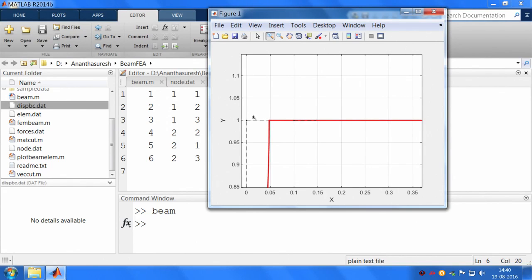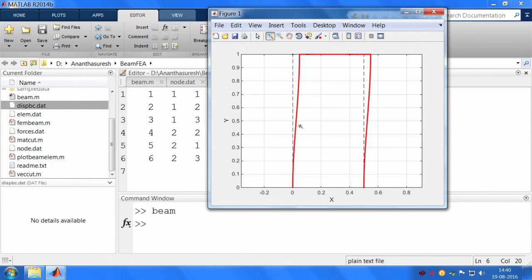That is the nature of the linear finite element analysis. We have to run this with the nonlinear finite element code in order to see the more realistic one, because this structure in reality is going to have this block not only move in the x direction, but also move a little in the y direction, which is not shown by the linear analysis. One more thing before we go to nonlinear code that you need to notice is that from here to here